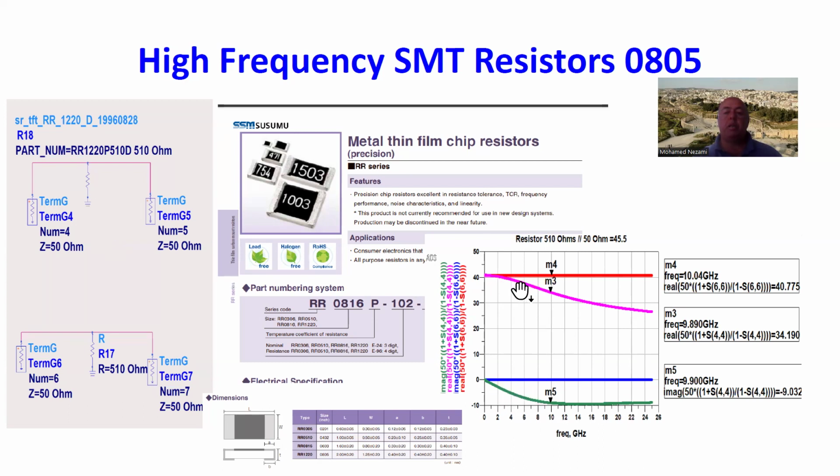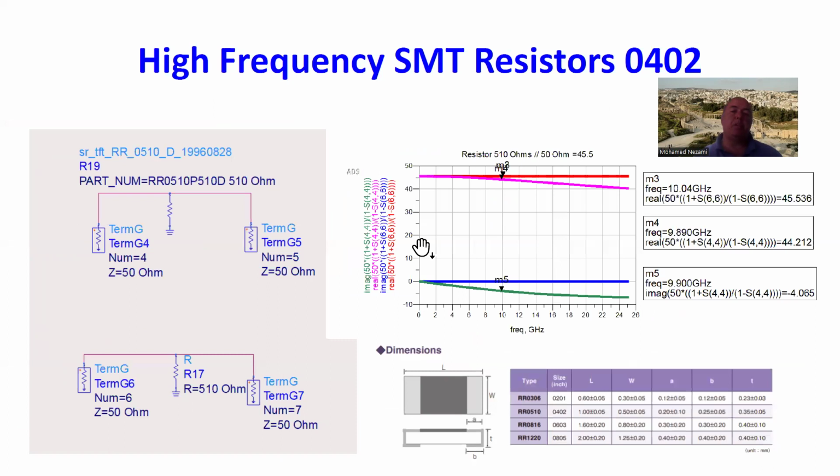And you can see that as you come in to 4 gigahertz, you're getting a real resistor, but beyond that, you're starting to get capacitances, and that's what you're getting in here, all these capacitances. And you end up with, say, only 25 ohms at the upper frequencies where we were operating. And that's part of the issue, okay?